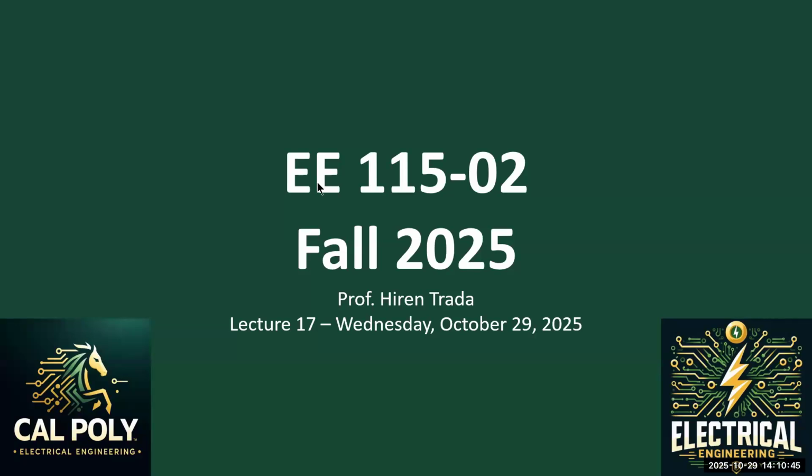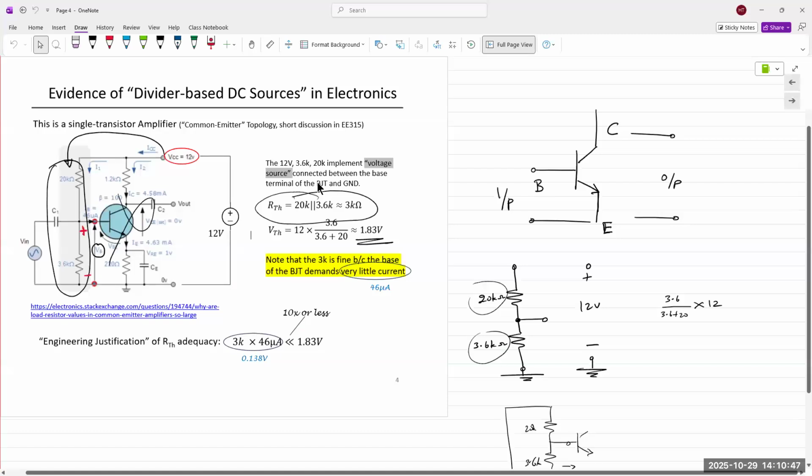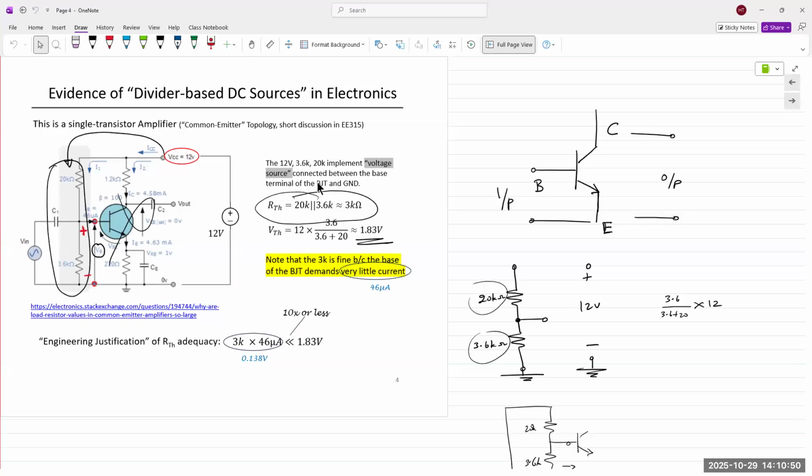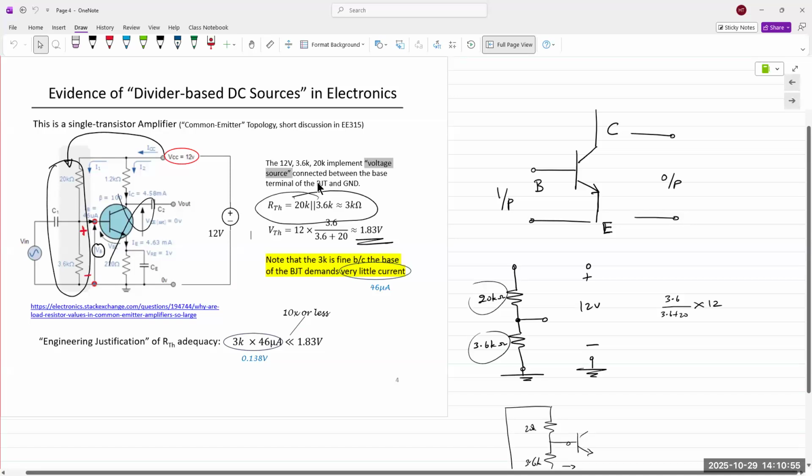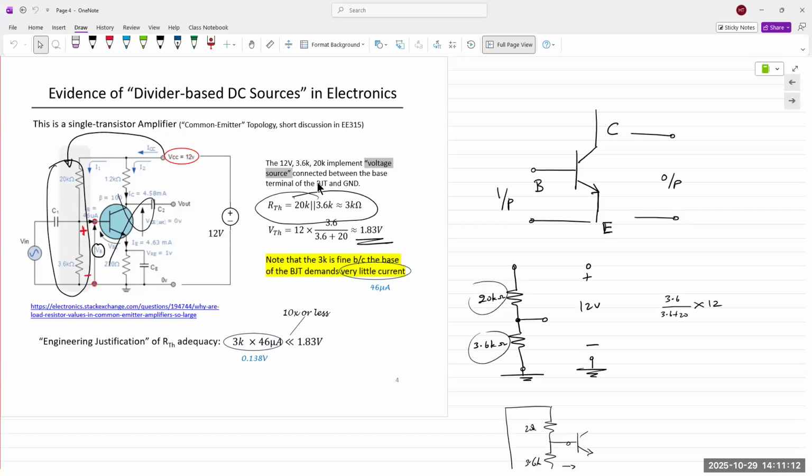All right, so we had looked at resistor applications in a voltage divider network. All of these follow the same principle. We have two or more resistors connected in series, and we apply a voltage to the series connection. Current passes through all of them and remains the same, but the voltage gets divided. In most circuits, we'll use a minimum of two. Obviously, we can't have less than two resistors, but most of these circuits just require two resistors to create a separate output voltage based on the input voltage that we're applying, right?